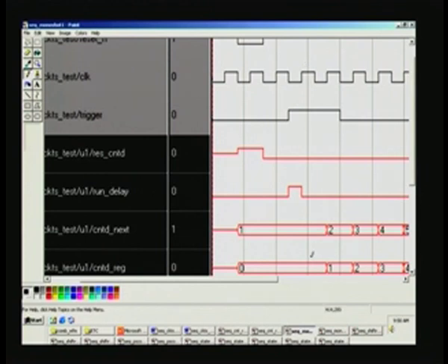Trigger P is nothing more than a previous trigger. That is how we compare the previous trigger and the current trigger, and then decide that it is a rising edge. So the rising edge detection is limited to the clock period, so it can't act faster. If you are designing a complicated system such as a programmable logic controller, we may encounter hundreds and perhaps thousands of IOs. In such a case, so many IOs might be on this rising edge direction, and for that you can implement it in this fashion.